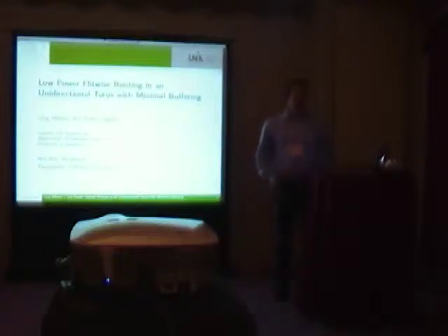I will talk about the network on chip as an alternative router design, and in future we plan to connect to the real-time, but this is not our route. So this alternative router design is motivated because we want to use network on chip in the embedded space, where the cores or the processing elements are smaller, and so the routers should be smaller too, because there is a relation between the size of the router and the core. So the core is smaller, we have to use smaller routers, and this is one possibility to make the router smaller.